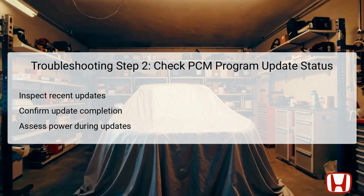The next step involves assessing the status of any recent PCM program updates. This includes inspecting whether the update process was completed as expected, or if any interruptions occurred due to power loss. This is crucial as the DTC P0602 signifies an incomplete programming sequence. Review the vehicle's service history to identify any recent updates and confirm whether any potential interruptions may have transpired. Additionally, check the power supply during the updates. Any fluctuations or interruptions in the power source may lead to the programmable state becoming corrupted. By fully understanding the update timeline and status, the technician can better gauge the steps needed to rectify the programming issue.